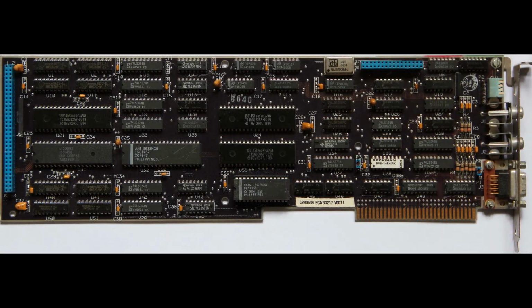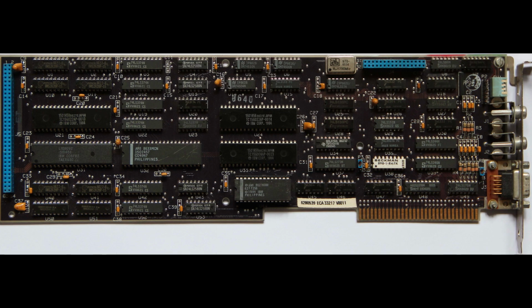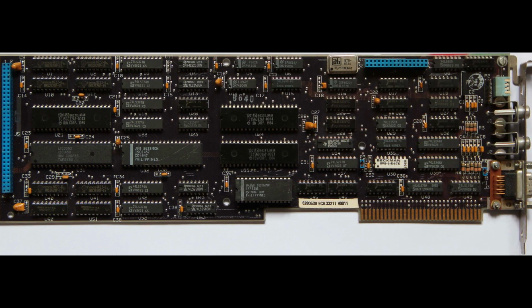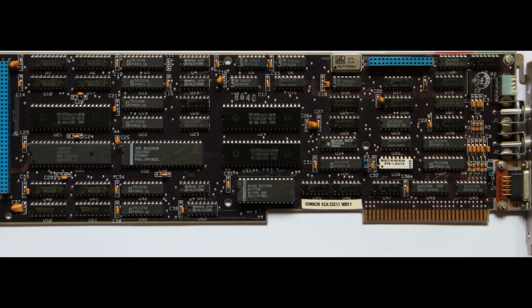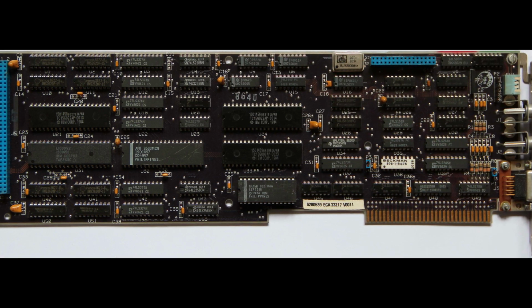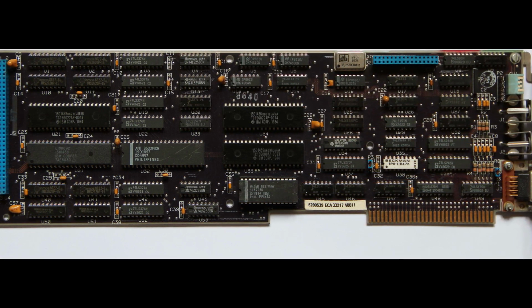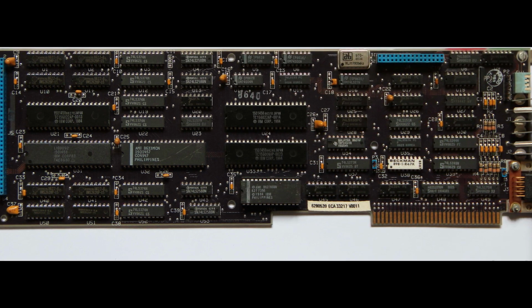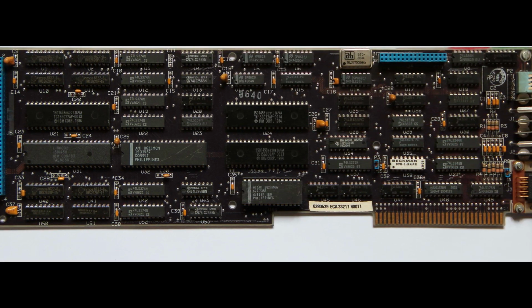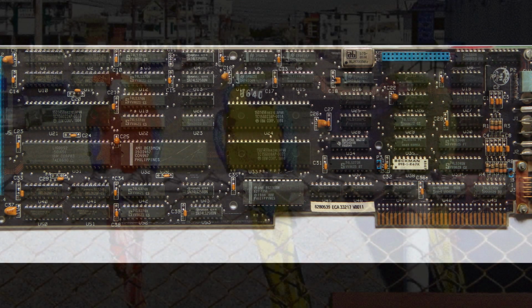It was really a big step forward because it united the best of the CGA and the MDA, and on top of that they even stepped forward. The maximum resolution was increased to 640 by 350, the color palette was increased to 64 colors, and finally the IBM engineers made it possible to select the displayed colors from the palette.